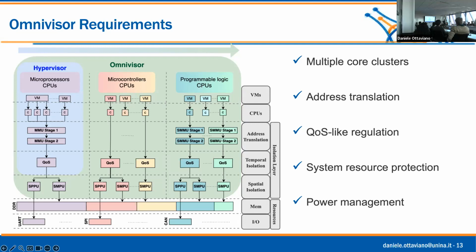Normally you see the port as a 6-bit ID, but actually it's 10, and the top bits are asserted for you. Exactly. So you understand who is the manager talking to you, and then you can activate the so-called, in the Xilinx jargon, poisoning of the